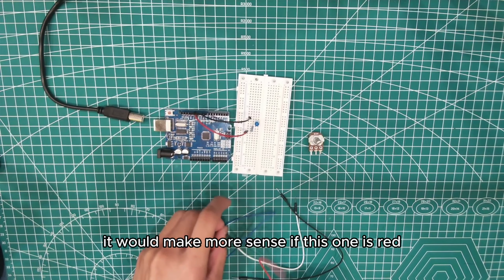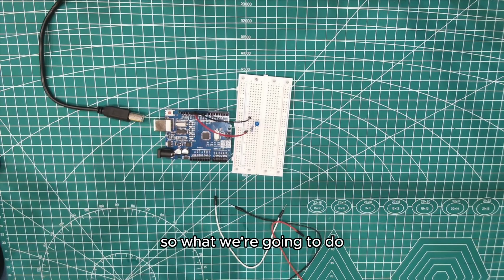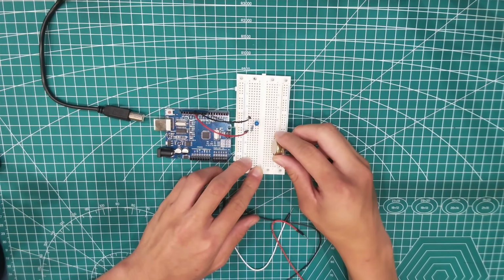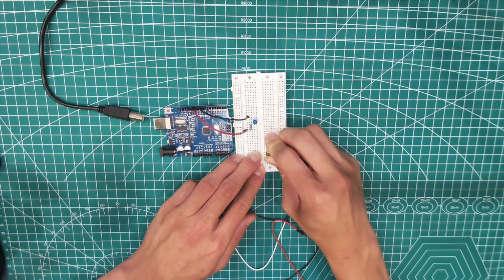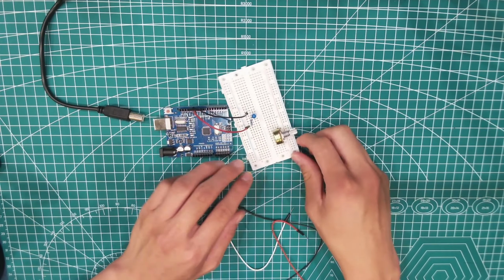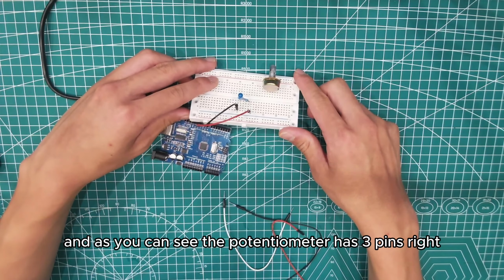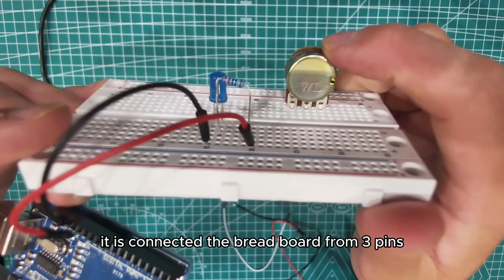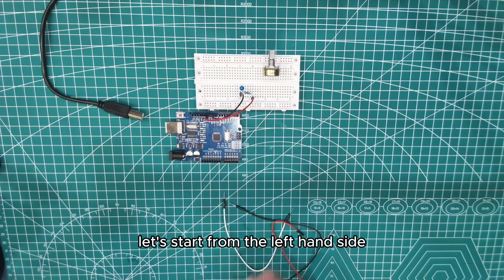It would make more sense if this one is red. So what we're going to do is put this potentiometer into our breadboard. So I'm going to put it right here. And as you can see, the potentiometer has 3 pins, right? So as you can see here, it is connected to the breadboard from 3 pins. Let's start from the left-hand side.